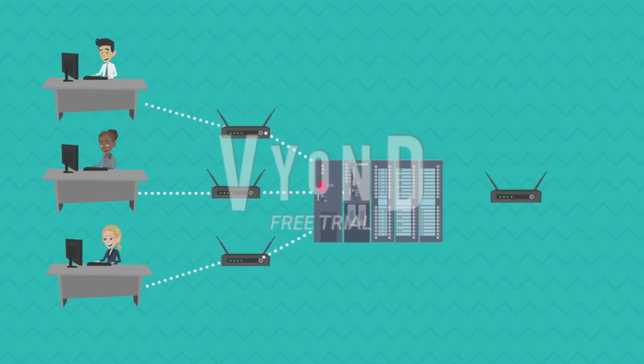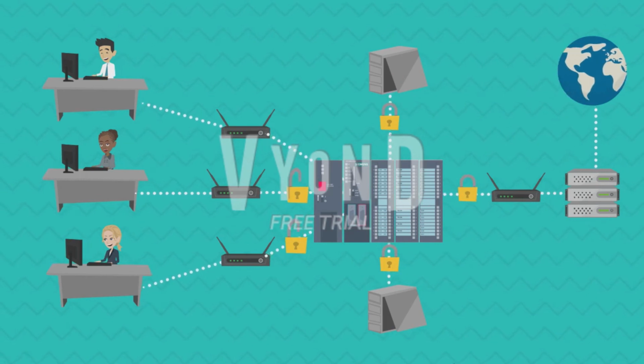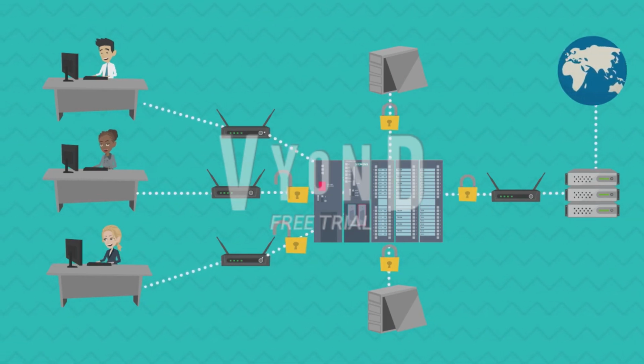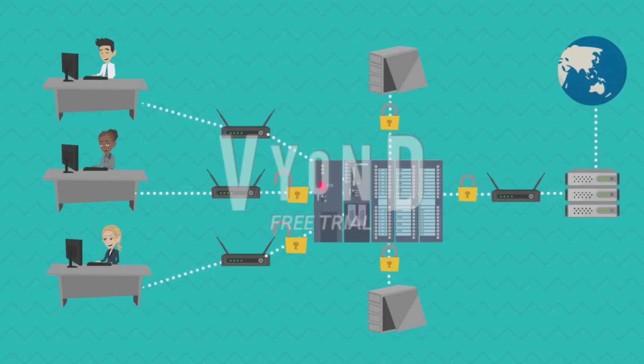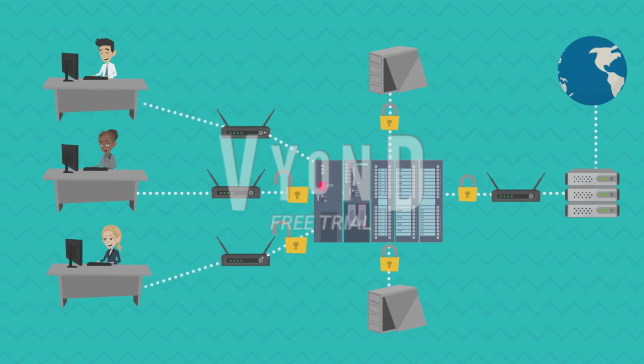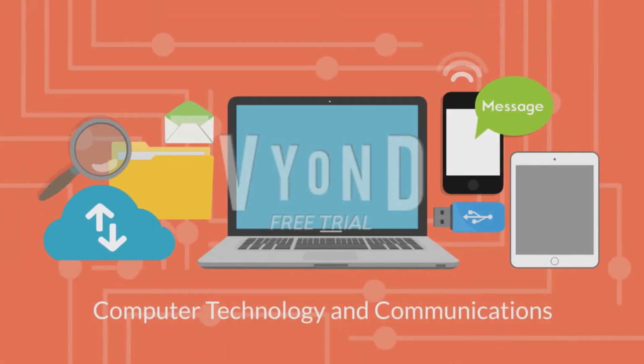In addition, all of the access points to critical system must be limited only to those necessary for system function in order to minimize the total number of access points available to attacker. For example, hardware communication ports like USB and serial ports. The number input and data generated by digital control system is a valuable commodity. Thus, routine backup of critical data is an essential part of any cyber security program.